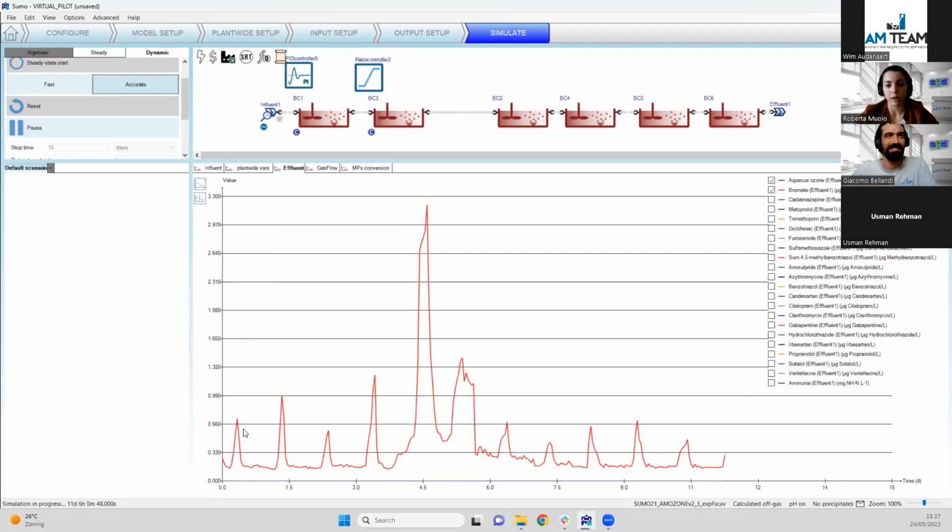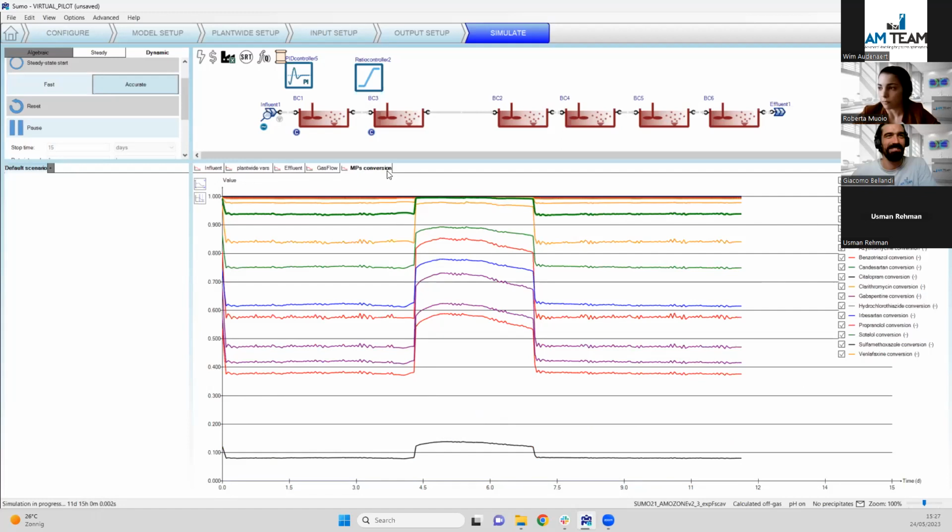So when ammonia is lacking, bromate peaks can appear. This is even more pronounced during the rain weather condition, not only due to ammonia, but also due to a particular behavior that happens during the rain weather condition in terms of radicals.